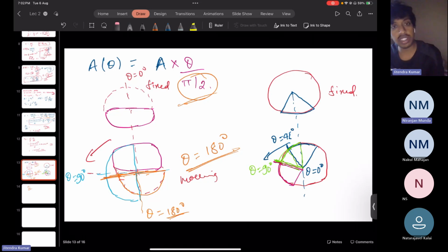So in common capacitors, we can use circular plates. There is no issue. You might have seen circular plates in 12th class physics also, but here there is no use of circular plates, because in common capacitors we do not want to apply any torque or we do not want our capacitors to move, right? So that is why circular plates are very common there. But here we want our capacitors to exert some force so that some torque should be produced and they should rotate along the axis.